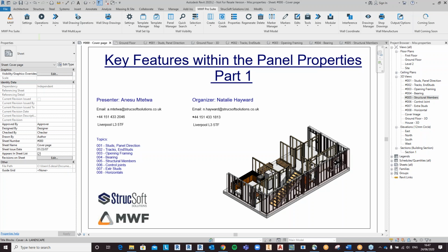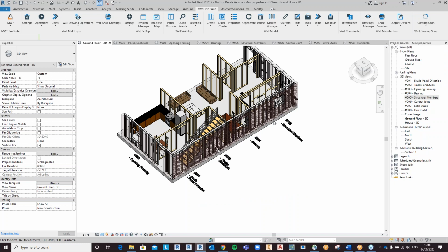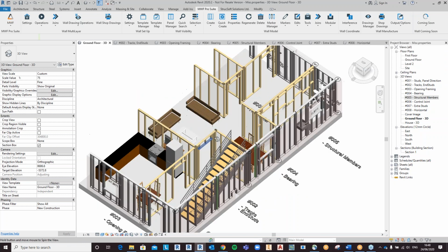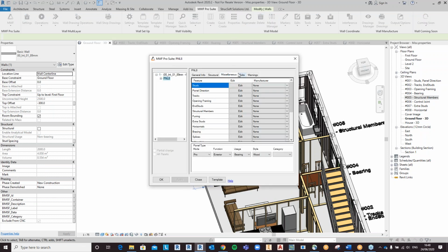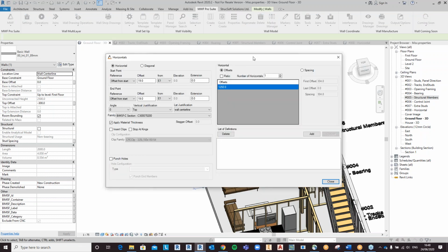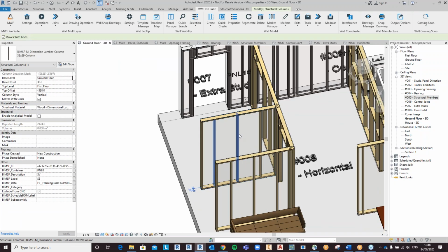We also had a question about the horizontals. Do you always have those going all the way through the panel, or can you have them starting at certain members? As I said, you can actually dictate where your horizontals are going to be landing, depending on your needs. So if I go back to my 3D, we can use this wall over here, for example. If I click my properties and go back to the horizontal, let me select where we want them to stop and start.